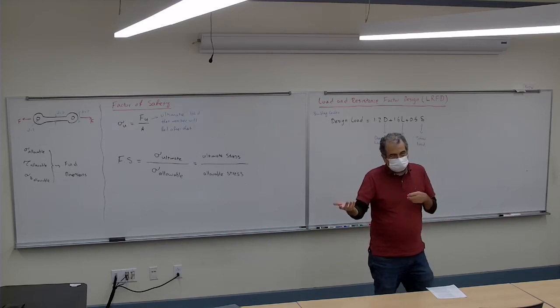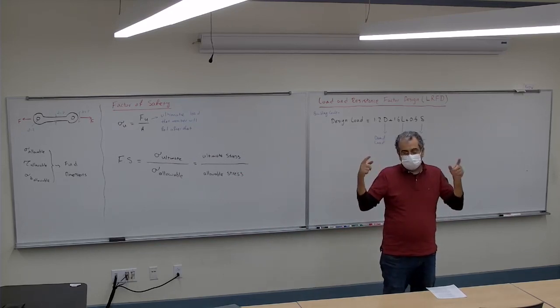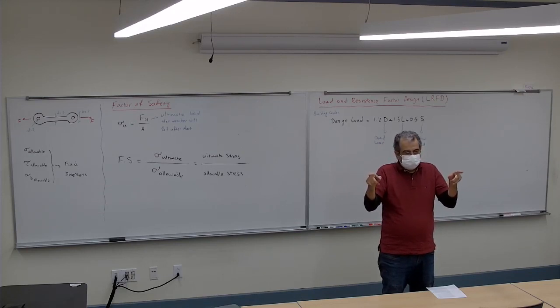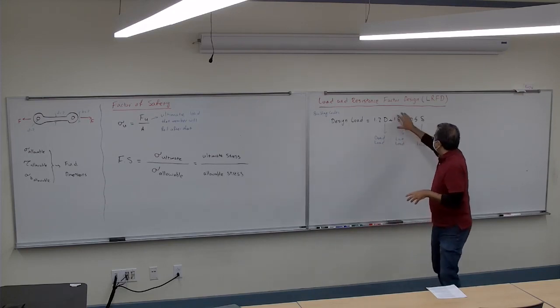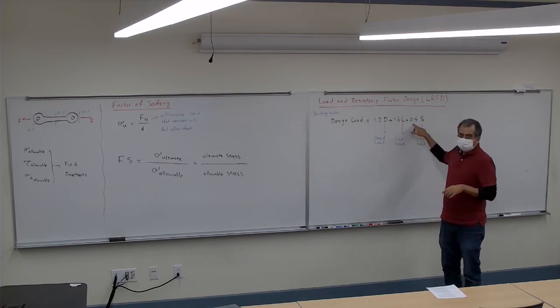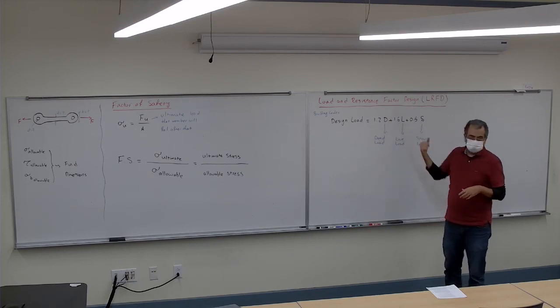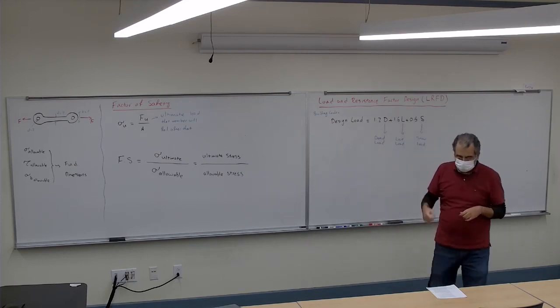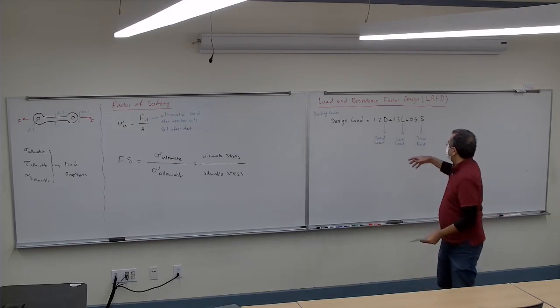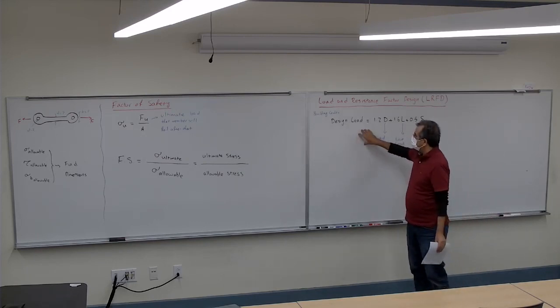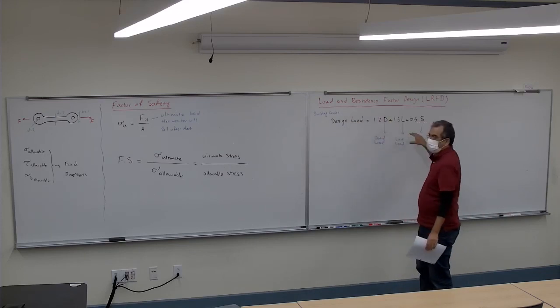So when you design the dome, usually you don't have a live load there. Yeah. So in that case, because you take that out, then probably you cannot put 0.5 there, because you remove that. You remove that 60% out of that. And again, when you have the design, you go to the building code, the federal code that tells you how you have to combine these.